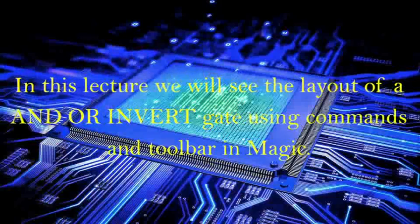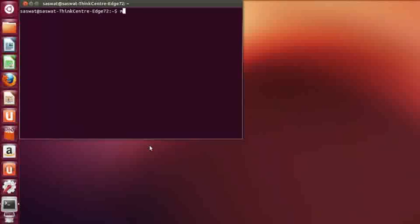In this lecture, we will see the layout of an AND-OR-Invert gate, that is AOI21, which is drawn from the twisted schematic. So at first, open the terminal window by pressing Ctrl, Alt and T. Then type magic, press enter.